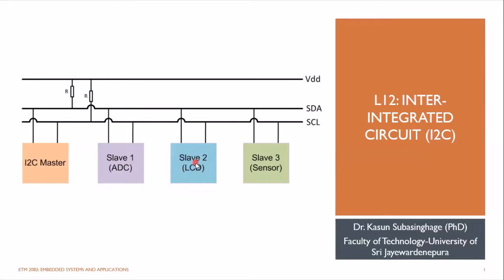Sometimes, if you have worked with an LCD, you need plenty of wires, but you can have LCD screens which have I2C capability. So you just need to connect two wires. Some sensors like temperature sensors, EEPROMs, memory cards and everything can be communicated with your microcontroller using the I2C line.